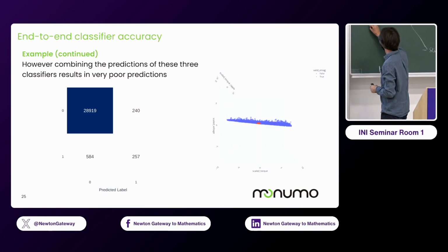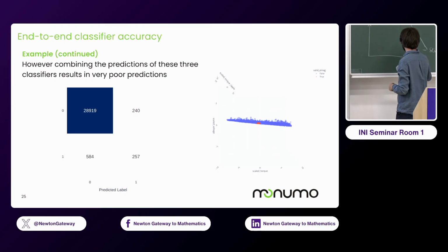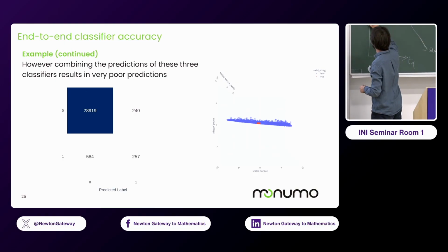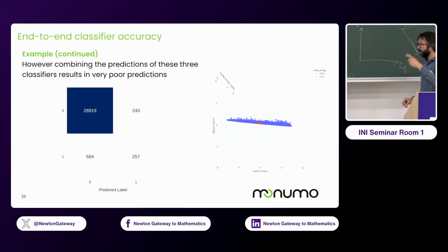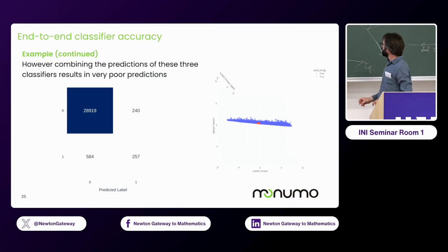at the torque versus voltage. There are negative coefficients in there, so I'm going to do it this way: torque versus the voltage you need in your simulation. Basically, the more torque you get, the more voltage you've put in with your inverter. So these points are going to be very highly correlated. And the good design is a design that will have a large torque for a small voltage.